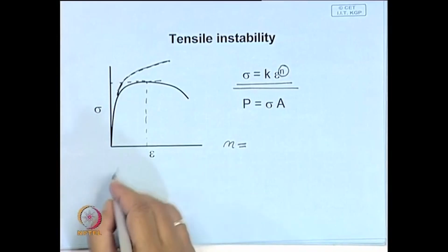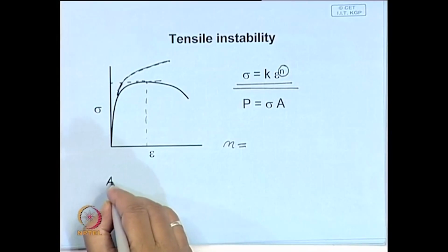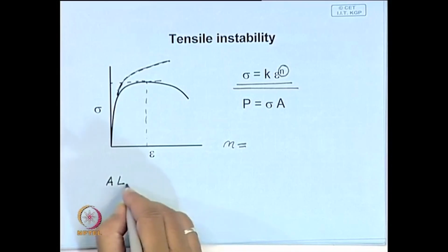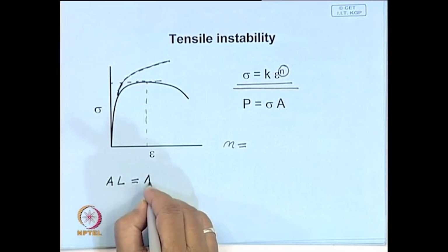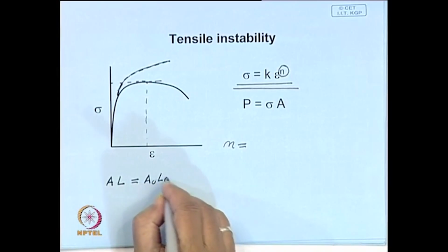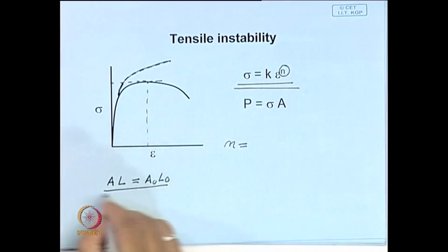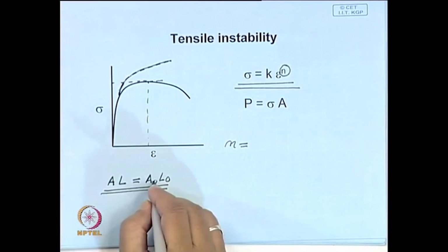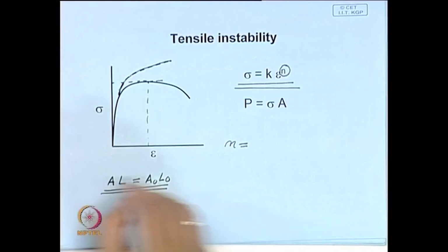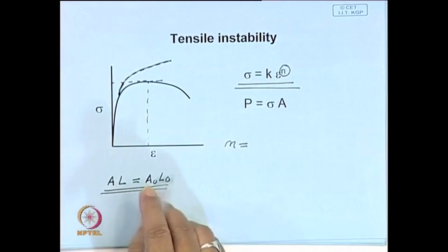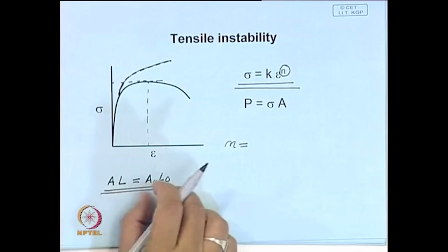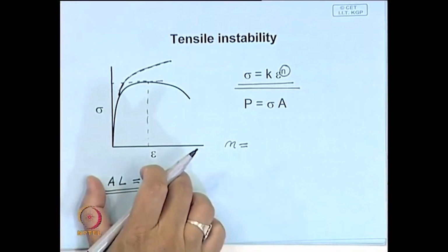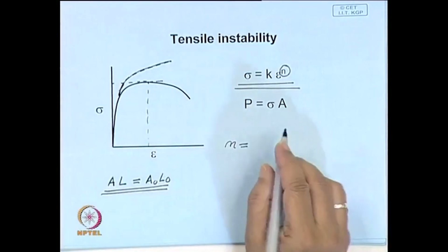The uniform elongation means, as has been mentioned, this area at any instant times the gauge length. This relationship you can make a conversion, I mean from change in elongation can easily be converted into reduction in area. But once necking starts, you have to be careful, although there is no volume change, this simple relationship will no longer be valid.